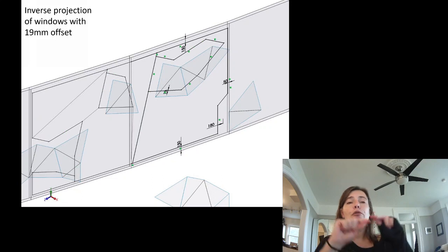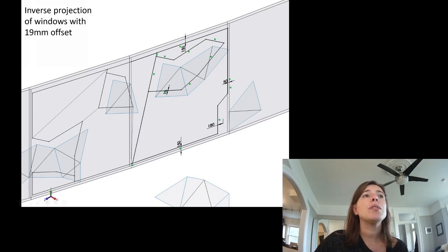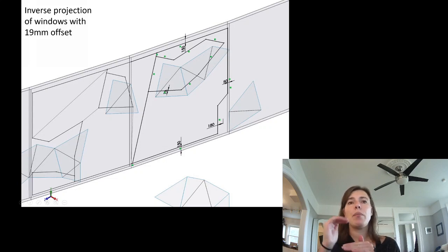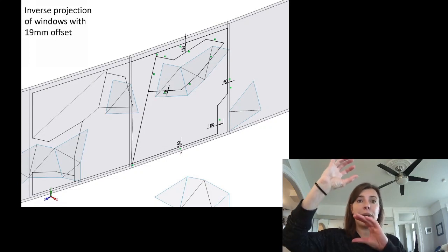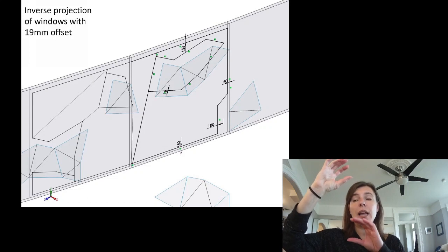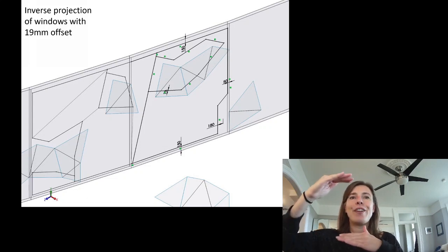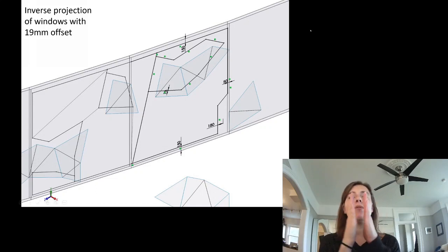And then I framed my opening. We also needed 150 millimeters from the concrete edges, from above and below. That's to give us our ability to slip it into those tabs that I showed you in the construction element, but also to have it fit on the truck. So we kind of built that element within the truck, and we needed 50 millimeters in between our panels to build in tolerance.